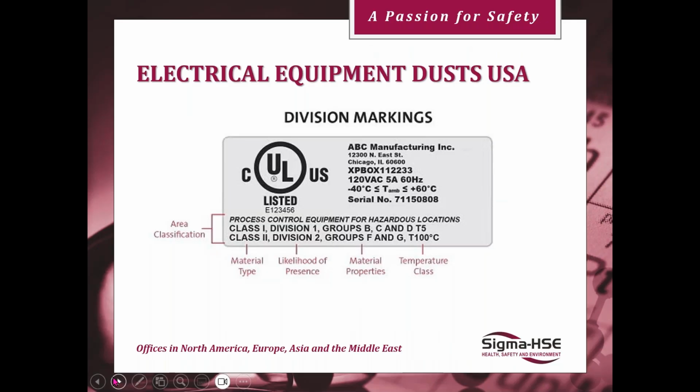We talked about division 1, division 2. Material properties, there's a whole range of them going across, and the temperature classes. So you've got groups B, C, D for the gases and vapors, and a T5 definition for temperature class. And then for the dusts, you've got groups F and G and the actual given temperature.